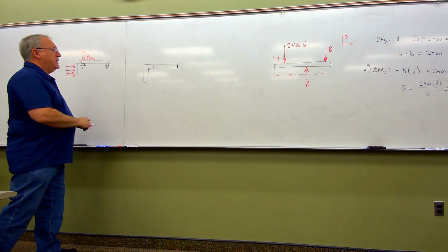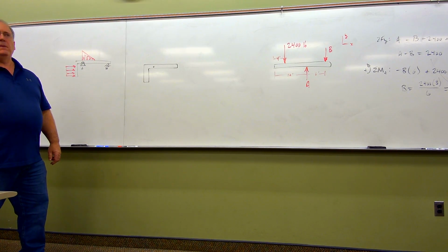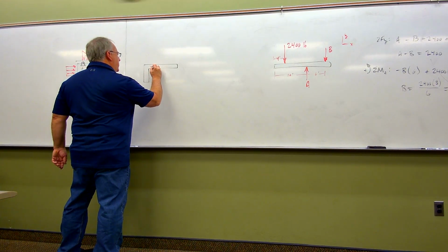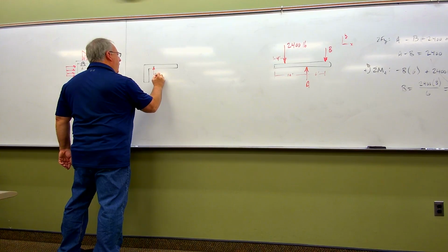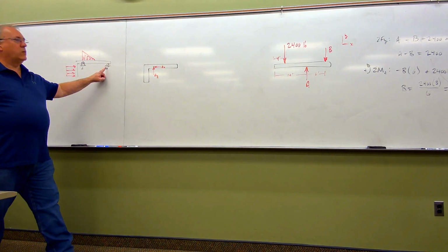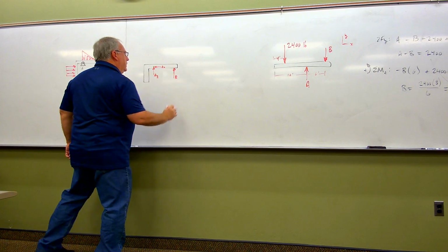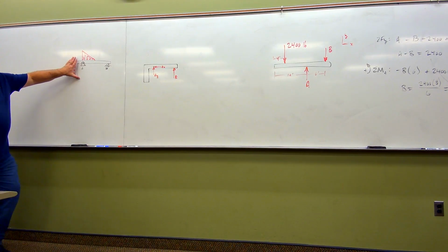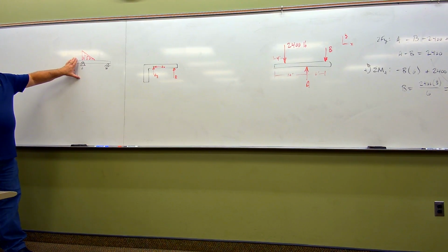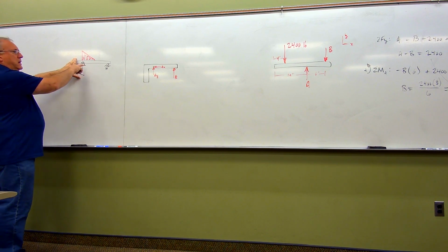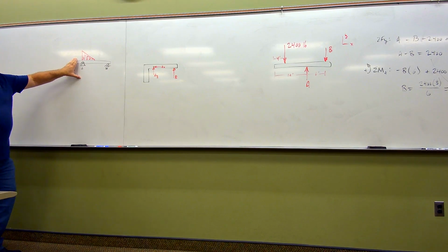And so if you think about what the free body would look like, I've got a pin here at A, so in the nothing's-new department, I'd have an AY, maybe some sort of an AX on it like that. Over here at the roller for B, I would have a single force. So again, never mind the fact that the beam is L-shaped like this. Never mind that at all. But notice the free body diagram for the pin and the roller is just the same old, nothing's new, right?